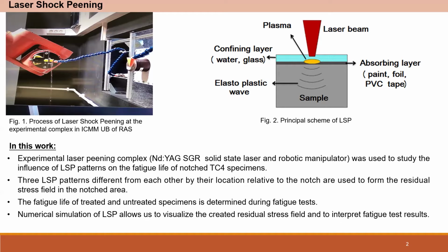Initially, the laser pulse affects the surface of the structure in resting water, and a layer that is less than 1 micrometer is vaporized. And in the second phase, the steam continues to absorb laser energy, and it's ionized into high pressure plasma.